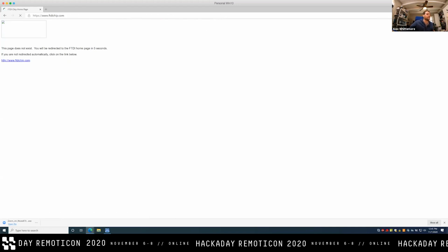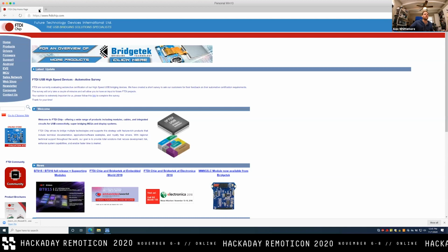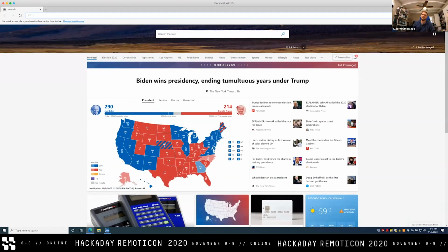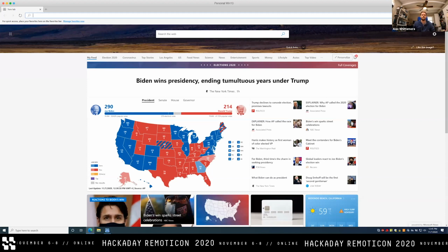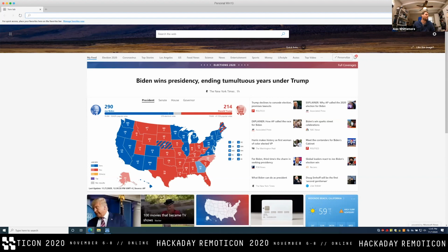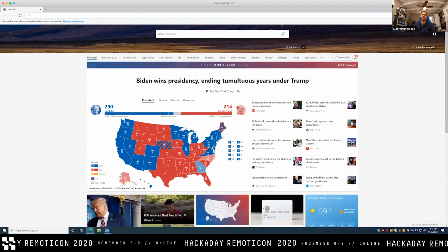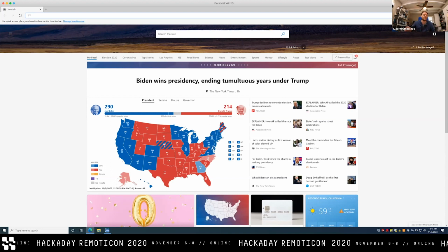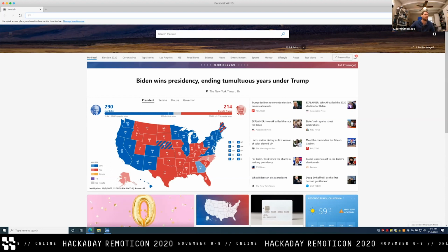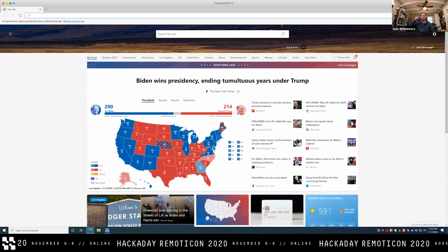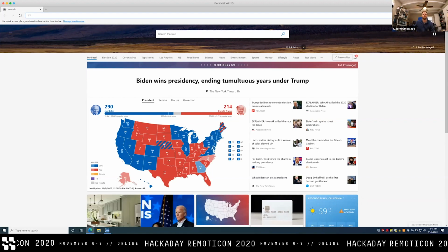Okay, well, anyway, long story short, if we look at the data sheet for the FT232H, we see, one, it does indeed use a 12 megahertz oscillator. So that thing that had 12 on it and looked like an oscillator was a 12 megahertz oscillator. Surprise. It also has a couple of interesting features where it pipes clocks out on a couple of different pins. So it has a couple of different clocks that it'll pump out. I don't recall exactly what they are, but one of them is a 60 megahertz system clock that all of the other devices in your system are supposed to be synchronized to.